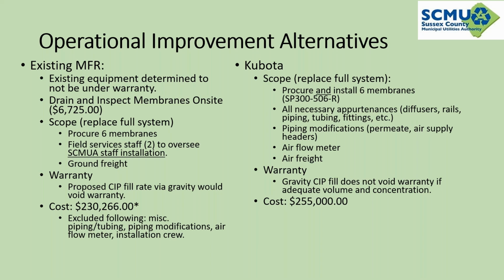That would mean they would see if there's any physical damage and whether the permeability had potential to be recovered, and then they would require us as operations to try to remove any of the air blockage within the diffusers. Obviously, as you saw in the previous slide, it was difficult for anyone to really remove the solids that were within those diffusers. So that was all tough to do.